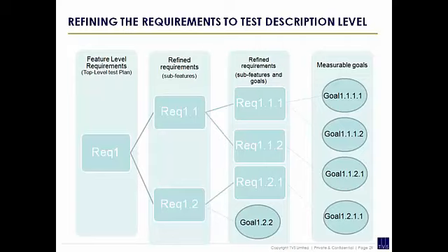So typically, if you're using directed test benches, this may be a directed test. You say, I'm going to write a directed test or two directed tests to verify this requirement. And so what you've now got is you're mapping these down onto directed tests. That doesn't work with advanced verification techniques because you haven't got directed tests. You've got random tests. And you measure the effectiveness of your random tests by your functional coverage or your assertions.